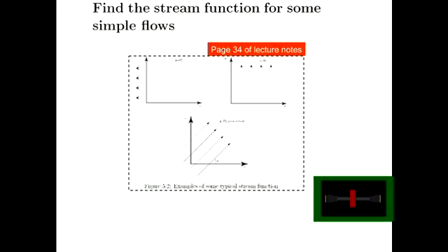So really, all that's telling us is that I can't just define any random flow field and have it satisfy conservation of mass. Okay. So that psi really is just an intermediate variable, which is a relationship between u and v. It's a notation, really, which is a relationship between u and v, which is automatically going to satisfy conservation of mass.